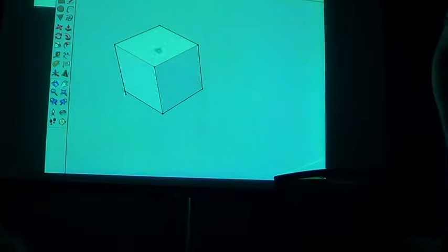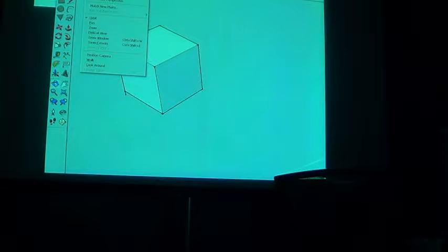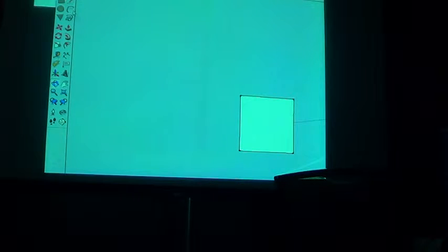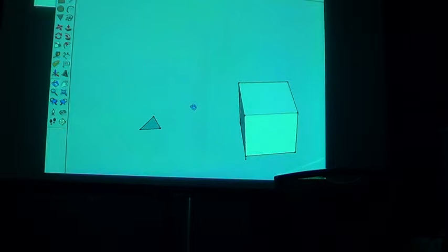For something that doesn't fit in their library, you can draw it by hand and then extrude it. You don't have to use squares. If I look at a top-down view, I love this, it doesn't update the screen until I click. So you can freehand draw stuff, and you can punch in angles, lengths, distances. The only thing that SketchUp usually prefers is that you create a polygon with a minimum of 3 faces. If you don't do that, it won't highlight that section blue, and there's no way to really extrude it easily.